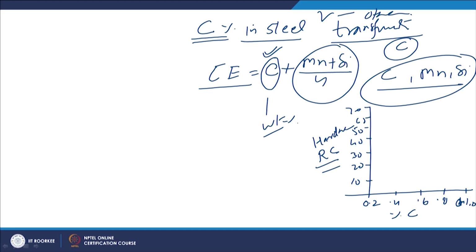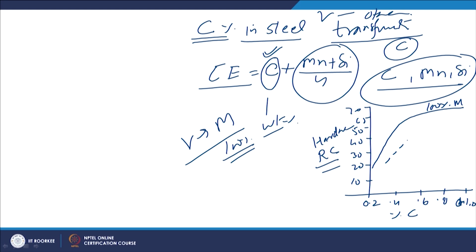When the high cooling rate typically observed during welding facilitates complete martensitic transformation, meaning austenite to martensite transformation is complete and there is 100% martensite in the weld metal, the hardness variation in steels goes like this. And when the martensitic transformation is 50%, there is of course an increase in hardness, but the rate of increase is low. In general, increasing the carbon content increases the hardness, and the increase is more effective when 100% martensitic transformation takes place as compared to 50% martensitic transformation.